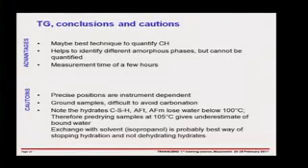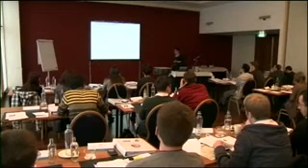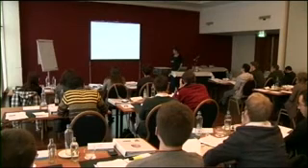As I said before, when you're grinding your samples, it's difficult to avoid carbonation. You need to be aware that most of your important hydrates, in fact, lose water below 100 degrees C. So if you pre-dry to 105, you're going to get really complete nonsense. Probably the best way of preparing samples is by exchange with isopropanol. This is a technique we'll talk more about in course 2, which is probably, to our way of thinking, the best way of stopping hydration and yet not too much dehydrating hydrates.